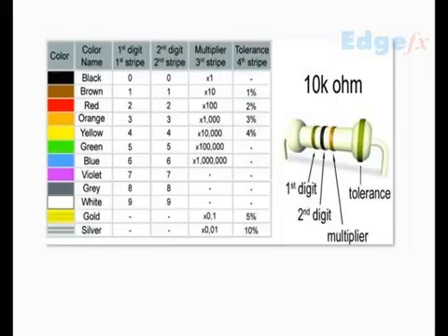Each value in electronic components has basically two parameters. The most important parameters are two. As we see in the resistor, it has the ohms indicated and the wattage also. The wattage means it is I squared R, and once it's I squared R, the more the wattage, the bigger the surface area has to be. In the process, it has to be a bigger size resistor.